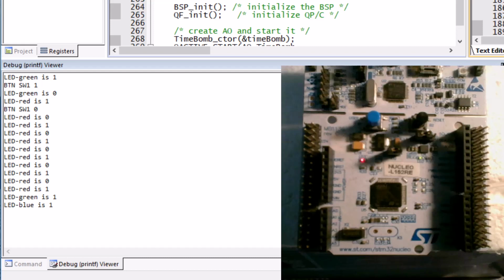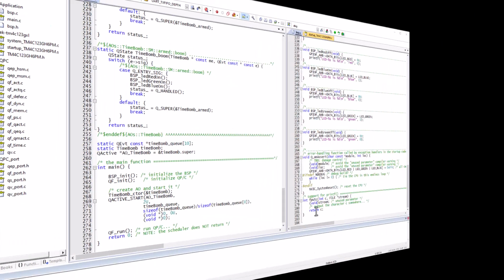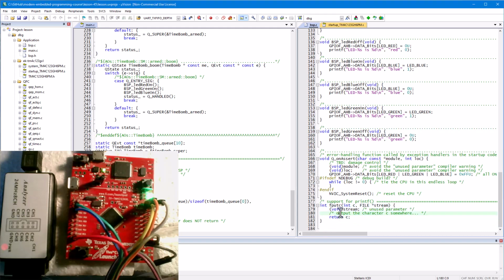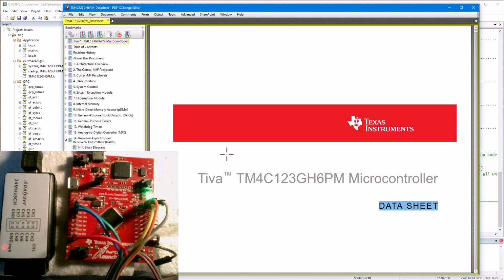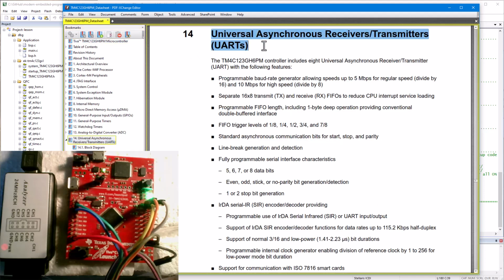While the programming was relatively simple, the method requires an appropriate hardware debugger probe, such as ST-Link, which is an external hardware to the microcontroller. Also, you must run the code under a software debugger, which then displays the output. For these reasons, often a better solution is to make the microcontroller produce the tracing output by itself, without any external hardware, which leads us back to the TivaC LaunchPad project. Here, specifically, you need to implement fputc using a piece of communication hardware already present in your microcontroller. This peripheral is called UART, which stands for Universal Asynchronous Receiver and Transmitter.